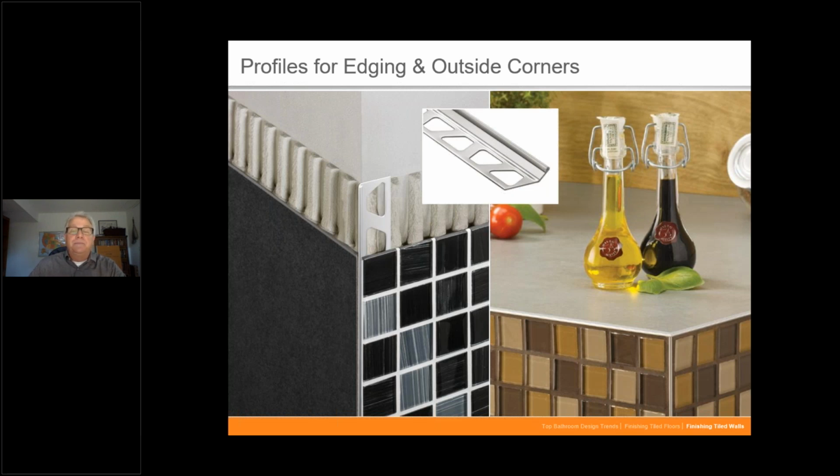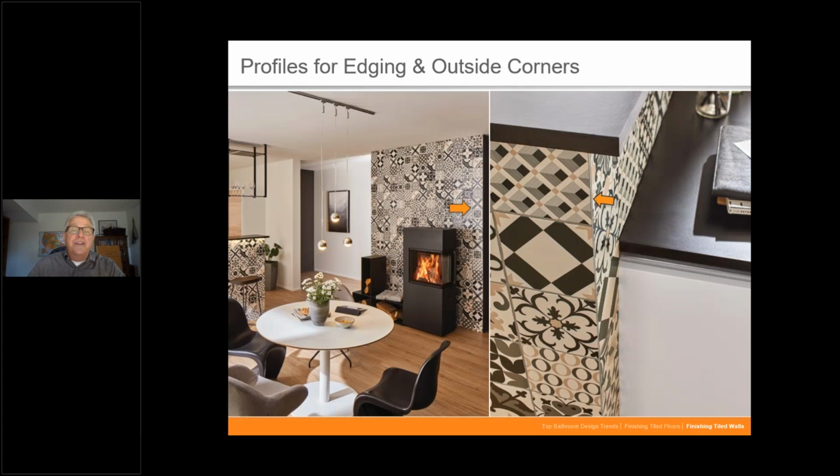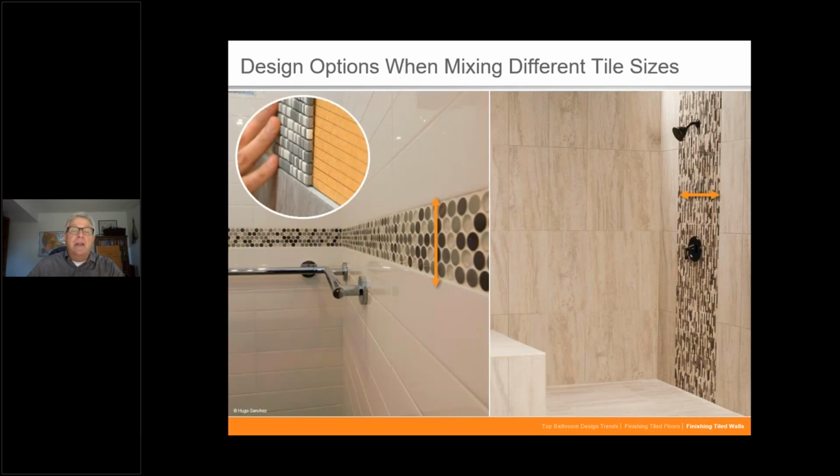protection of that edge. Also, if you have something where the design element is like some of these tiles with the designs in them like this, you don't want to interrupt that and ruin your aesthetic. So this is nice to incorporate that very fine little line edge into these types of applications. Another nice option that is being used quite often is to mix the tile, the different textures, colors, sizes, like you see in these photographs. So keep in mind that many of those smaller format tiles are much thinner than the other large tile you're putting out on the rest of the field. So you're going to have to come up with a way to accommodate the difference in thicknesses.